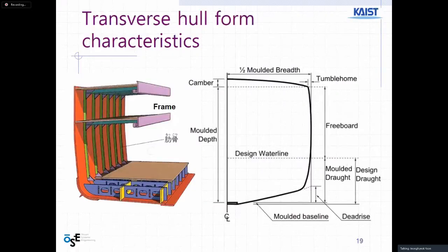And her form structure shape is very complex. So this is a double bottom tank top plate. And double bottom is very complicated because of, and this is a frame. Right? I explained this one. Each frame, right? And sometimes there is a bigger frame. So maybe here and here, maybe 3 times, 4 times larger frame is coming. So main frame and smaller frame between.